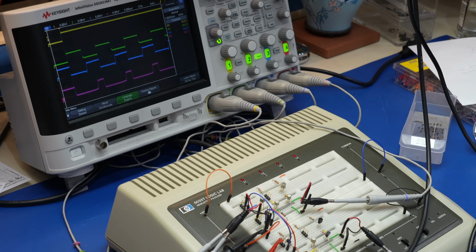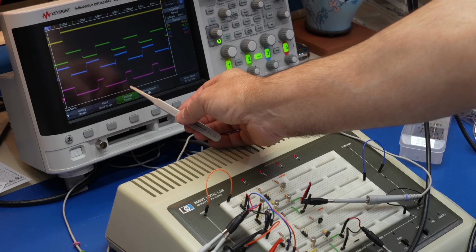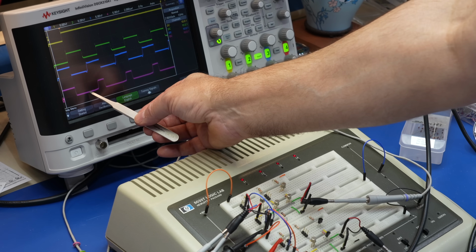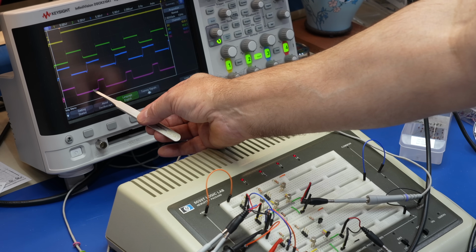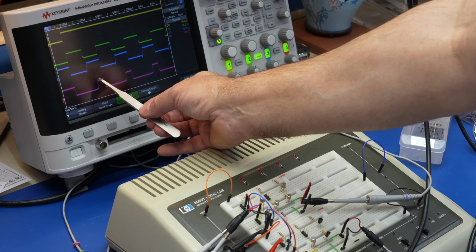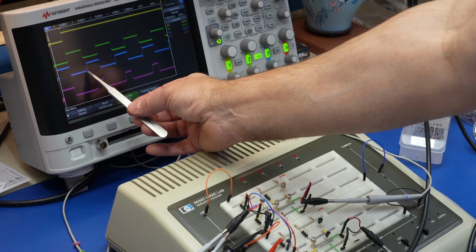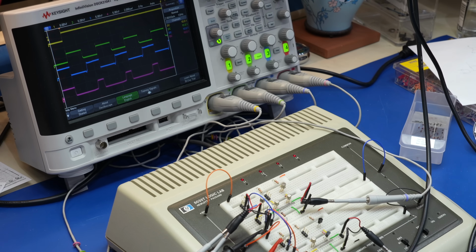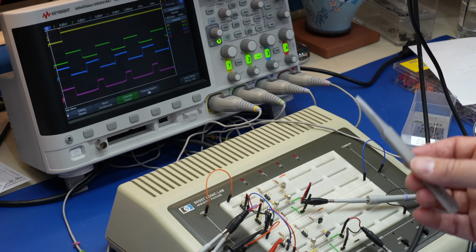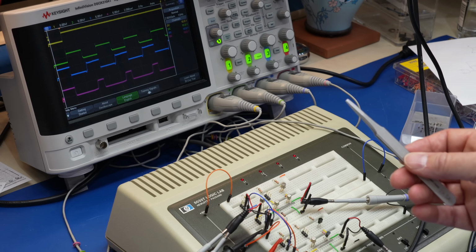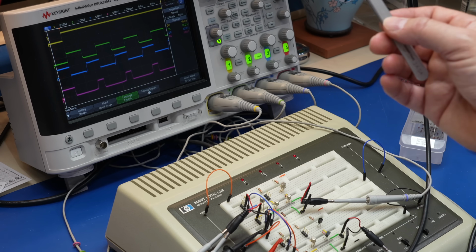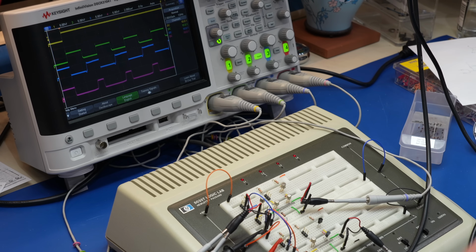Immediately you can see 2 things. First, my gates are miserable, but second, the DTL has a very large delay going from 0 to 1, and the TTL has a delay too, but it's much smaller. So both of my gates are slow right now, but you can already see the problem with the DTL gate that's fixed with the TTL implementation. The turn-on delay of the transistor logic is far smaller than that of the diode transistor logic.